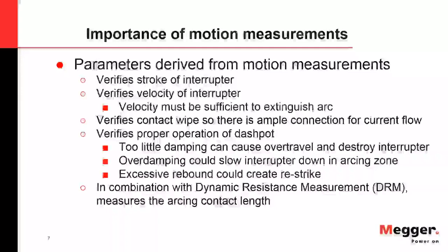You can have something where your signal comes in late, or let's say your coil's bad, so it takes a little bit longer to trip. But as long as it releases that trip latch and that spring and that mechanism gets going, as long as you have enough velocity during that interruption, you're going to be able to extinguish that arc.